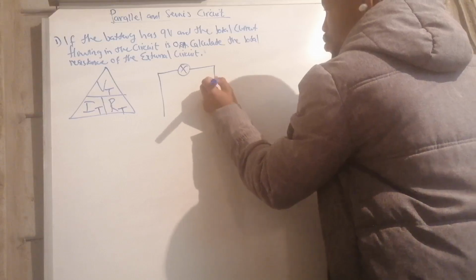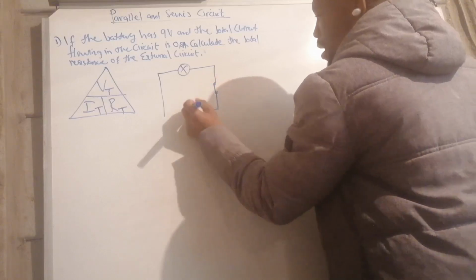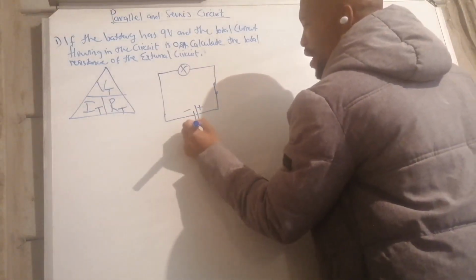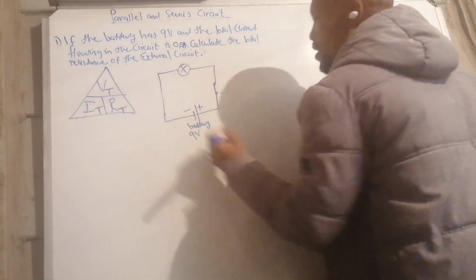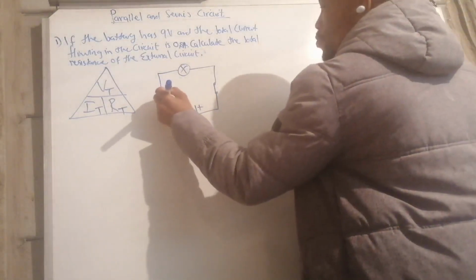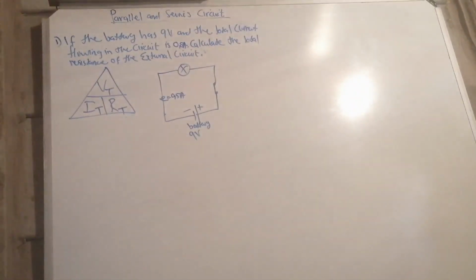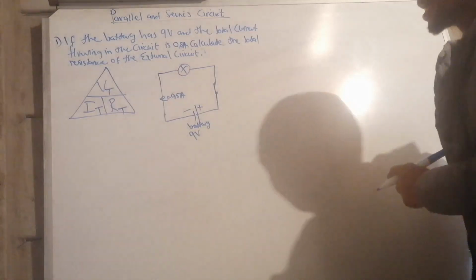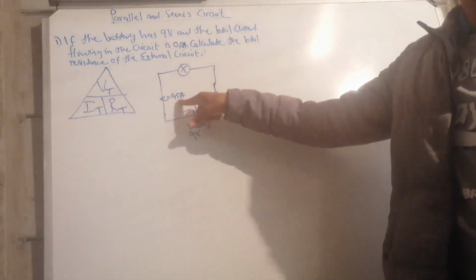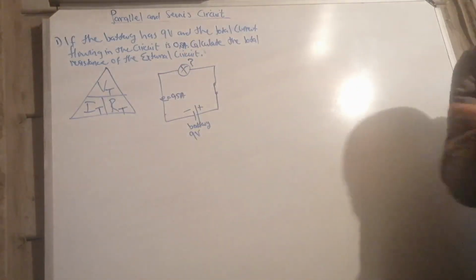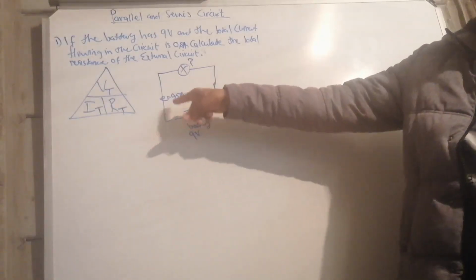Right, and then on a switch it closed. On a battery of 9 volts, how much current flows? 0.5 amperes. Again, current being the rate at which the electrons flow, how fast the electrons are flowing, passing through a point. Again, now we have voltage, current, and the resistance opposing the flow of the electrons, the flow of current.